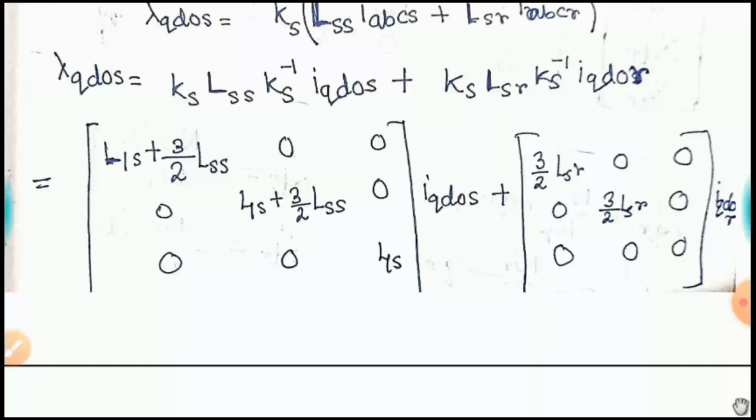But this is the difference between the synchronous machine and the induction machine. In the synchronous machine, unless you attach your reference frame to your rotor, the transformation from one reference frame to another won't give you much advantage.